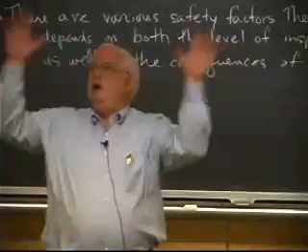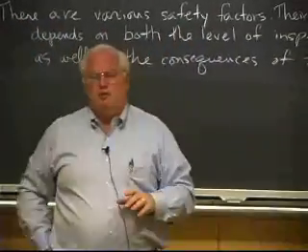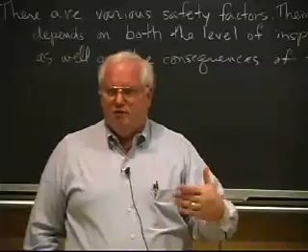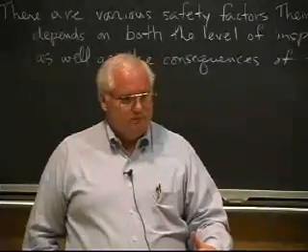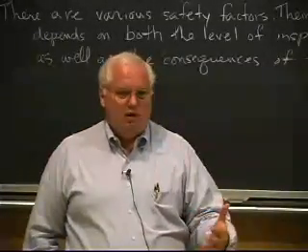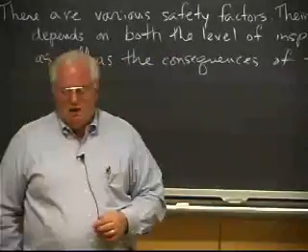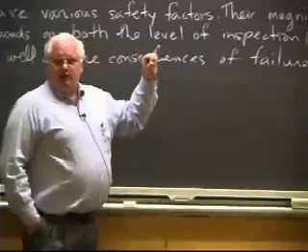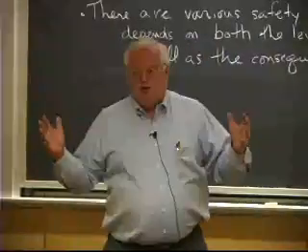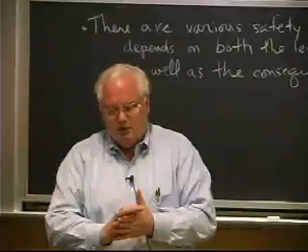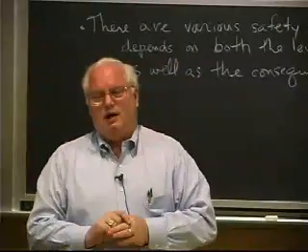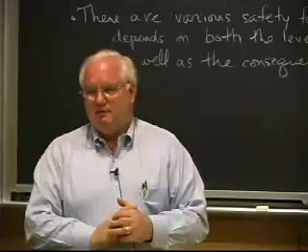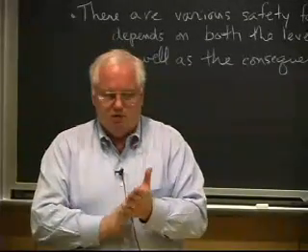To give you an example, joists, the beams that go up to hold the roof or the floor of a building, are redundant. So if one of them fails, usually the whole building doesn't come down. In fact, the whole building won't come down with a single one failing, even if they're all marginal. The safety factor for joists I mentioned was 5/3. Now, the typical safety factor for the rest of the building, the main beams and columns, is going to be a factor of 3 on design, actually 3.3, or 10/3 if you want.